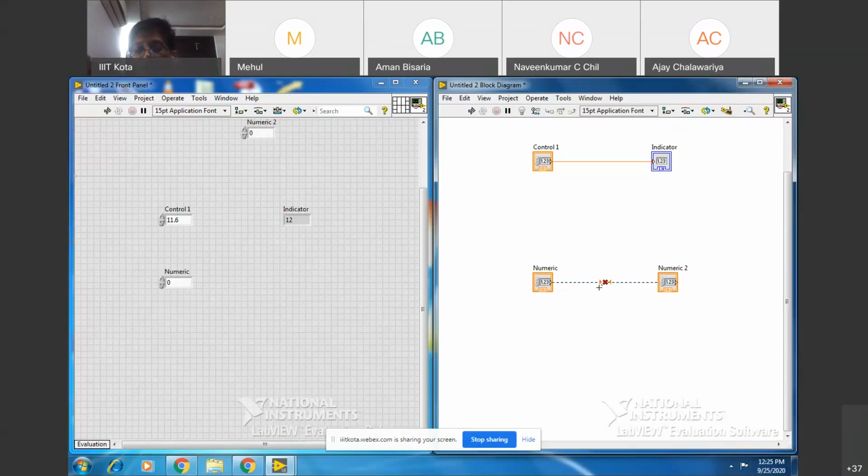So you have to highlight the wire by clicking on the particular wire, right? Just see, I have to click here. Now you can see the cursor is on the plus sign, meaning it is hovering around some free space. Have you seen one cylindrical object appear? The cursor has become cylindrical type. So if I click it and extend it, it is taking one connection.